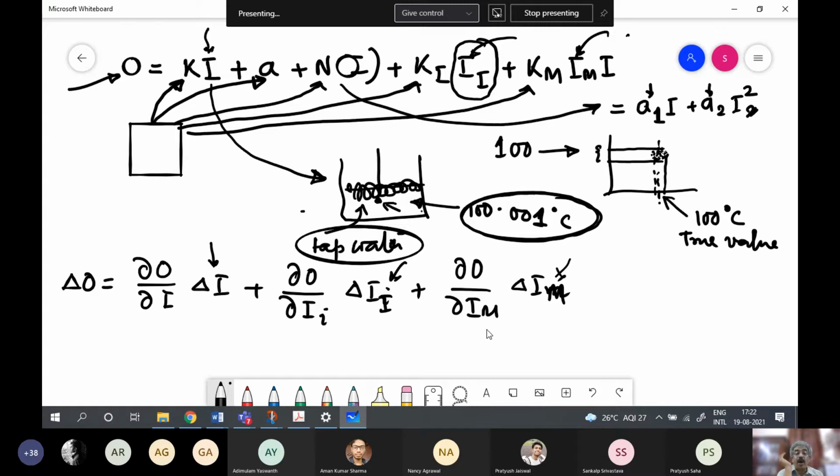So this equation. What I'm trying to say with all this is that when you are considering repeatability, you are considering the variations in the output. If you try to measure a temperature of 100 °C a number of times, suppose 50 times, you will still not get the same reading out of that instrument, because firstly there will be interfering and modifying inputs.